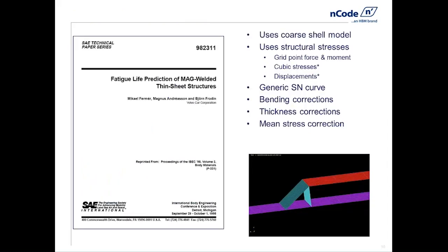As I had mentioned, DesignLife has had the ability to do weld analysis on shells for many releases. And the hallmark of it basically is the ability to represent the welds in the parts as a relatively coarse shell mesh. A meshing approach that would allow us to deal with literally hundreds of welds in a structure and be able to model an entire structure.